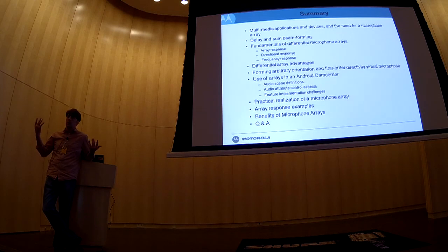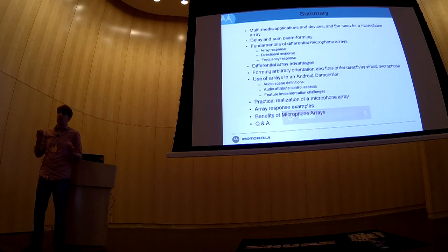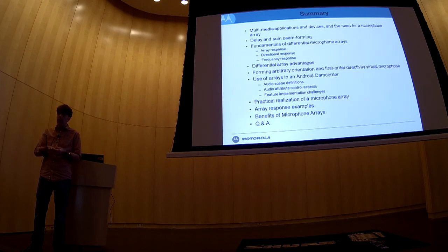And then what it does is some energy minimization in the bandwidth where the wind would occur, where it will decide between the multiple microphones in the frequency domain the signal from which bin would be useful in this case, because the signal that has less energy is most likely the one that has no wind noise present. And that works quite well in minimizing the wind noise.